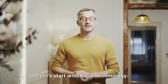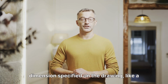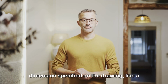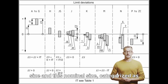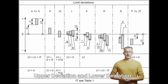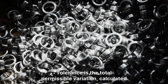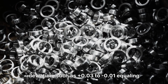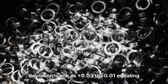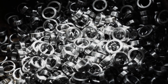Let's start with basic terminology. Nominal size is the theoretical or ideal dimension specified on the drawing, like a 50 mm shaft. Deviation is the difference between the actual size and this nominal size, categorized as upper deviation and lower deviation. Tolerance is the total permissible variation, calculated as the upper deviation minus the lower deviation, such as plus 0.03 to minus 0.01 equaling 0.04 millimeters.